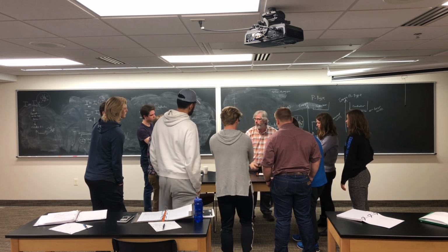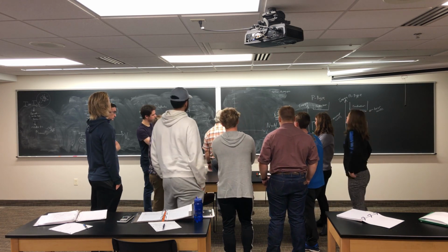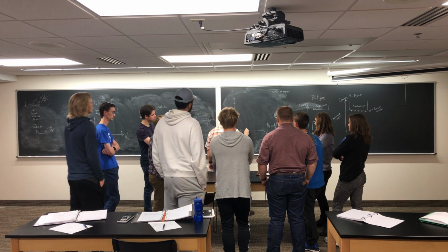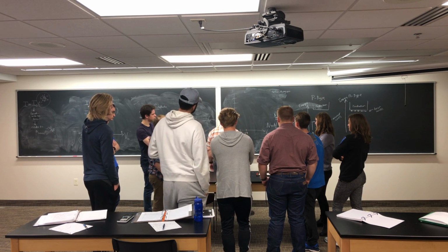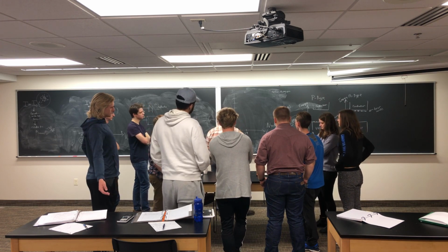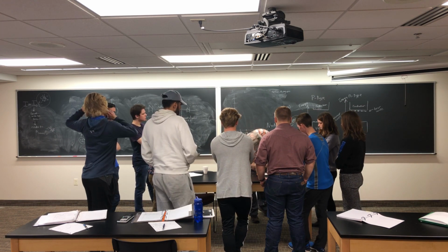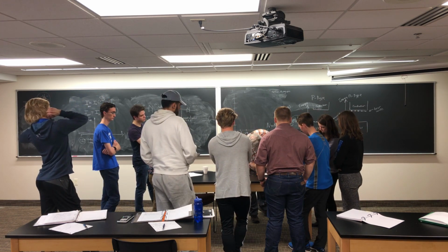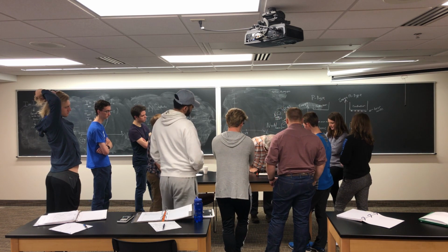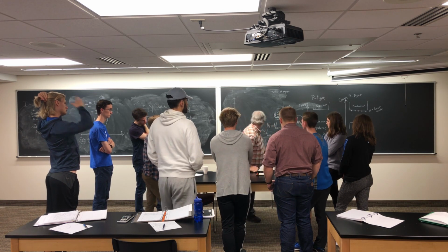Roughly at 0.7 volts. So I'll make this unit 1 milliamp. I get 1 at 0.7. So what if we go up to 1.4? Twice that. We should get more than just another milliamp, right? If it's exponentially increasing. So let's go up to 1.4. What did we go up? We went up not till 2, but we went to 2 point what? Oh, 3.3. Well, 3, yeah, 3.3. I think that's about right.